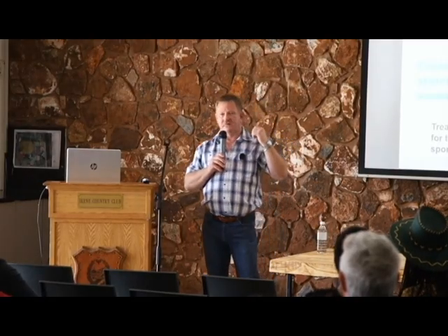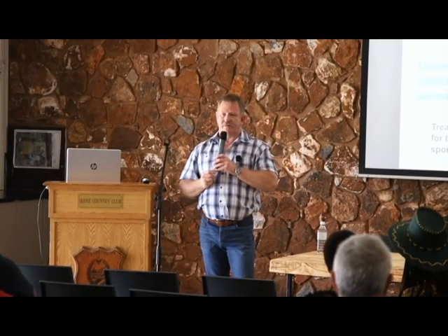And I'm speaking of practical sites that I've done in Cape Town. The one site used to use 18 kiloliters of grey water plus 12 kiloliters of municipal water per month in summer to keep the garden alive. That was in the old anaerobic grey water systems. With the drought in Cape Town, I designed and changed over to this aerobic system. I shut off the municipal line because there was a water shortage and said whatever survives on the 18 kiloliters of grey water must survive.